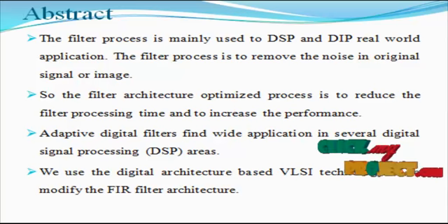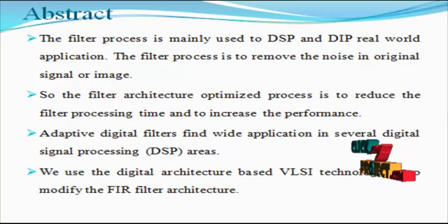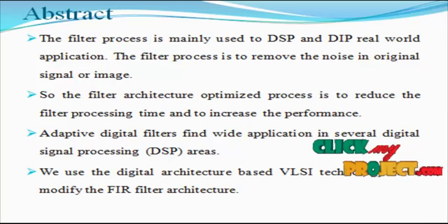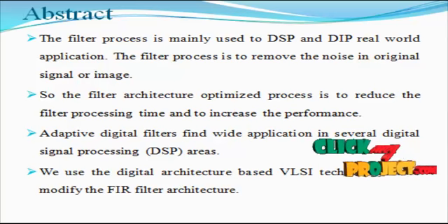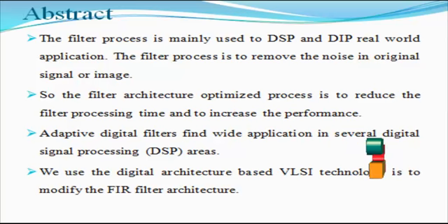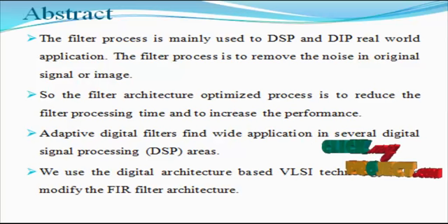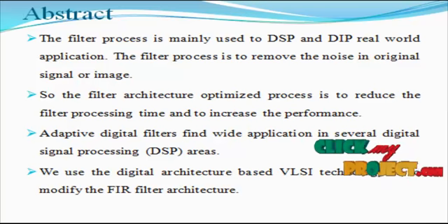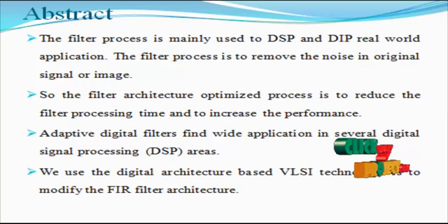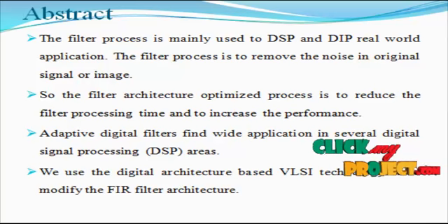The LMS adaptive filter is popular not only due to its low complexity but also due to its stability and satisfactory convergence performance level. Due to its several important applications, there is increasing relevance of constraints on area, time and power complexity, and efficient implementation of the LMS adaptive filter. This paper proposes a precise analysis of the critical path of the least mean square adaptive filter for deriving its architecture for a high speed and low complexity implementation.